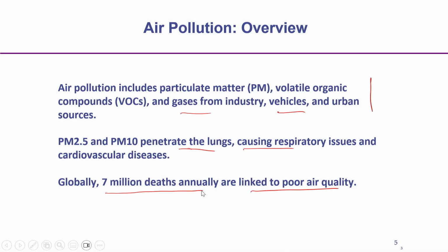We have to reduce this air pollution at the source, and in some cases that is not possible, so we have to protect ourselves by using different types of filters. Even at the source we should use a filter medium, and the textile filter is the easiest one which can be used.